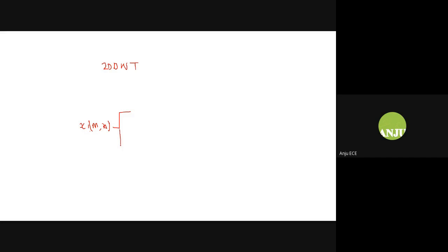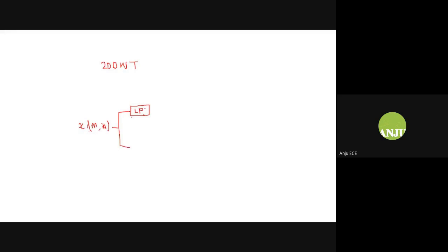Okay, it means that it's going to be with an analysis bank. I presume that people are familiar with decimators, interpolators, and sampling rate conversion, because you've learned signal processing already. So you'll be passing it through the filter bank and decimator. A decimator is preceded with an anti-aliasing filter, that is, an analysis filter bank.